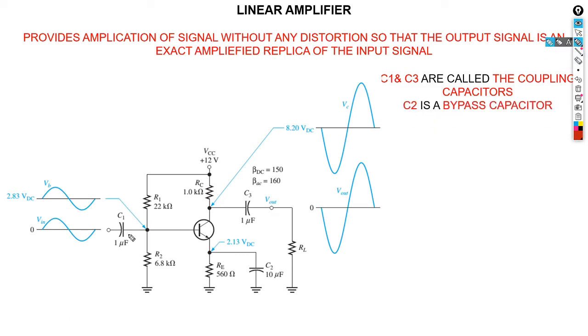Because when you come with your AC current, this current will flow here, and then once it arrives here, you can see that this is a closed switch. The current will take the easy path, the current will flow over this, and we are doing what? We are bypassing R1, and then when it's coming here, this current will go. This is a ground when the AC current is coming. Okay, and therefore our RC as well is connected to the ground, and then this is connected to the ground. Okay, so this is AC analysis.